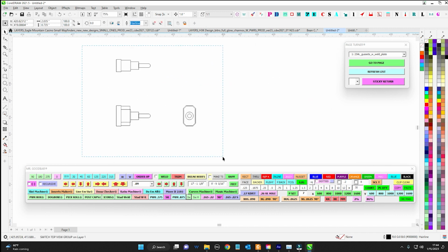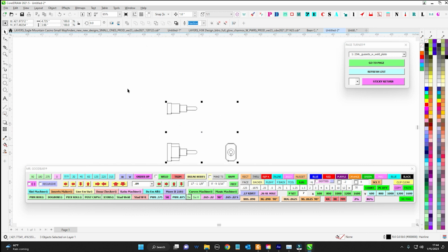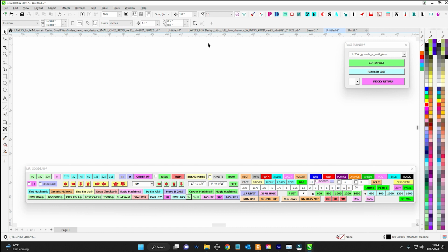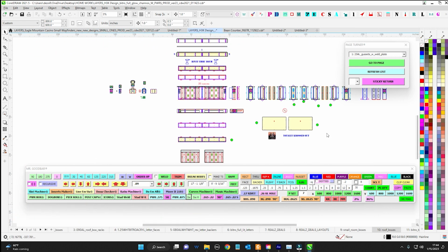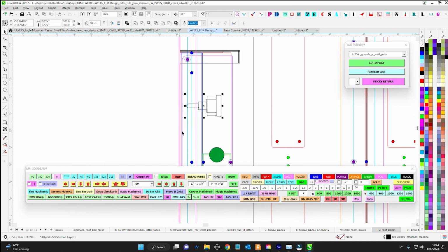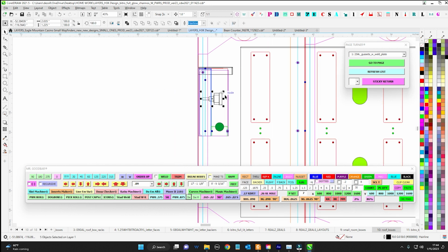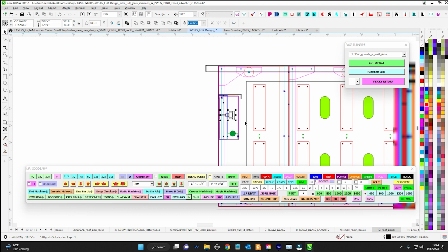So when I'm calling a switch, this is an actual profile of the switches we use, a snap switch. Like when I'm doing this right here, this is a power supply box for some signs we're doing. So we have a patent pending way of keeping the snap switch protected by UL inside its own little box, but it also recesses the switch back so it's not sticking out in the weather and the boot's getting beat up and things are happening to it, because snap switches aren't very hardy.